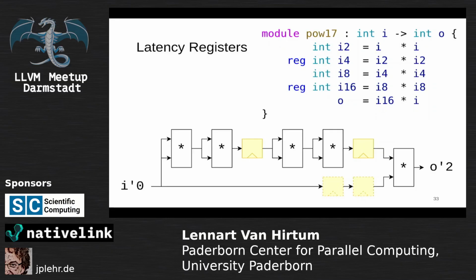This is a very common operation that we do in hardware design. And in many languages, it's surprisingly painful. So in SUS, what we do is we compute a value for every single wire in the design that I call the absolute latency of this wire. And then with the explicit latency count register annotations there, you tell the compiler, okay, between these 2 points, there has to be at least a difference in absolute latency of 1.